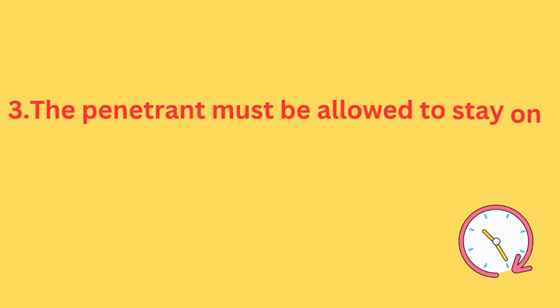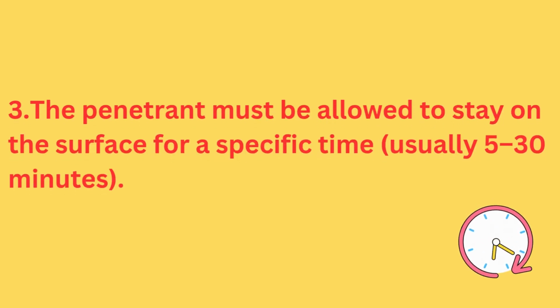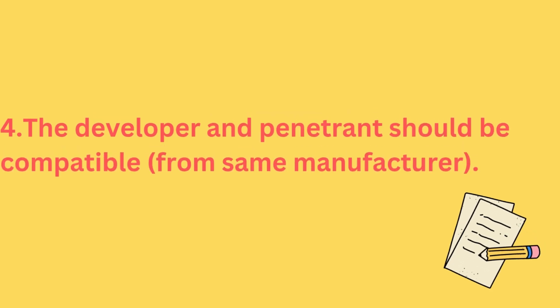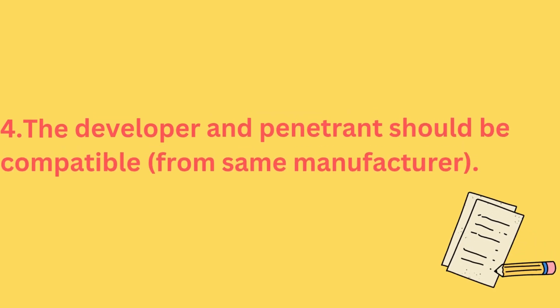3. Dwell time. The penetrant must be allowed to stay on the surface for a specific time, usually 5 to 30 minutes. 4. The developer and penetrant should be compatible, from the same manufacturer.